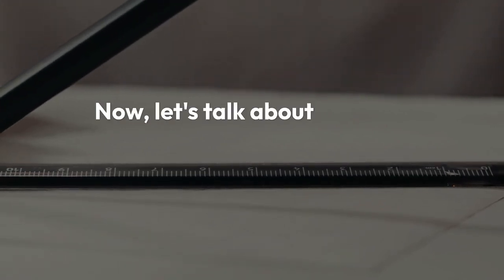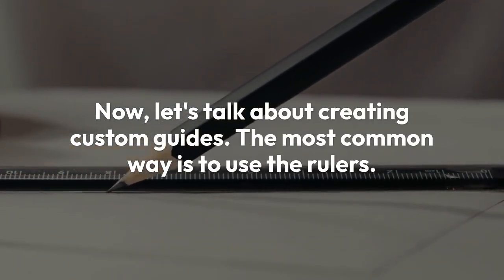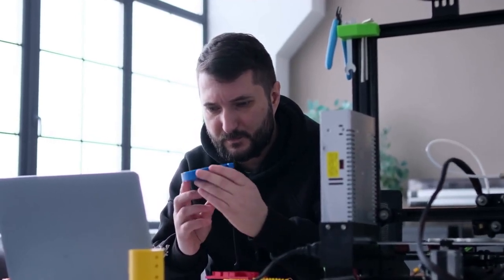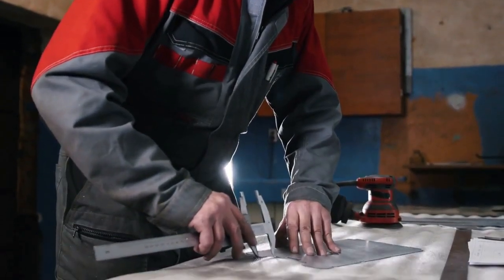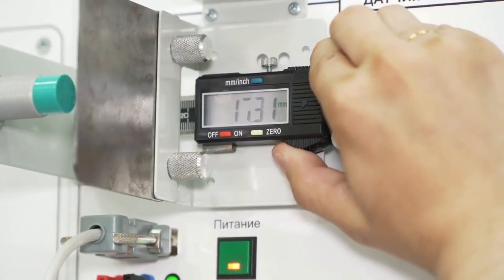Now, let's talk about creating custom guides. The most common way is to use the rulers. If your rulers aren't visible, just press Ctrl-R on a PC or Command-R on a Mac to show them. Then, you can simply click on the top or side ruler and drag a new guide onto your artboard. Place them wherever you need to mark specific alignment points.